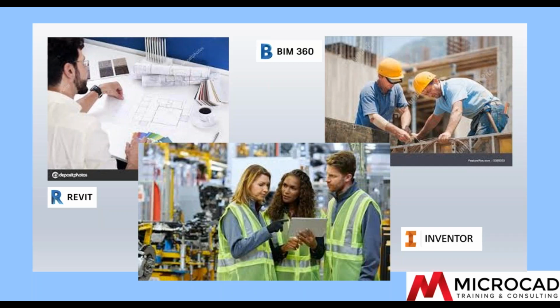The architect may have one idea of what, say, a railing system should look like for their building. He would then search catalogs for a matching railing. If there is a close match but not exact, the architect may define his unique requirements and load that into a BIM model. The manufacturer of the railing system would consider the architect's unique requirements and cost out the custom products.